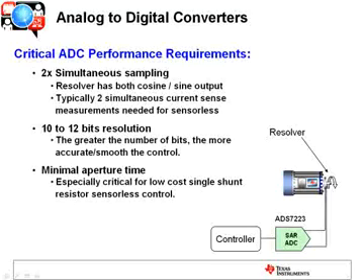Finally, the aperture time is also important on these ADCs. So the aperture time is how long does it take for that ADC to actually get a reading. And this is really critical in some of these low-cost implementations where you're using only a single shunt resistor. So you're only taking a reading off of a single, basically the bus, all three of them combined, and you've got to take two readings spaced apart.